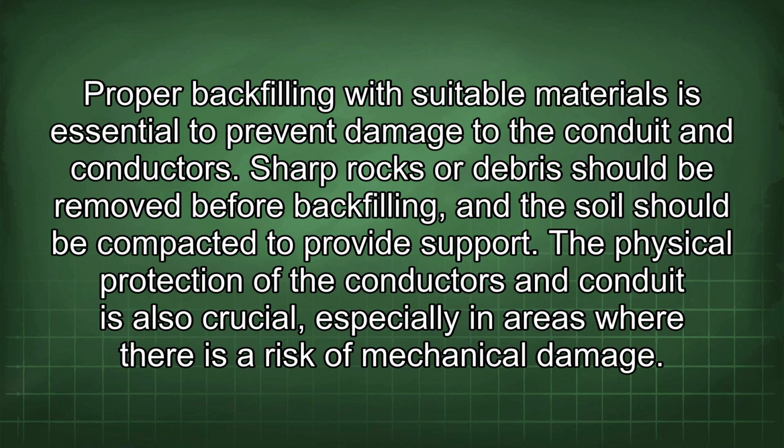Proper backfilling with suitable materials is essential to prevent damage to the conduit and conductors. Sharp rocks or debris should be removed before backfilling, and the soil should be compacted to provide support. The physical protection of the conductors and conduit is also crucial, especially in areas where there is a risk of mechanical damage.